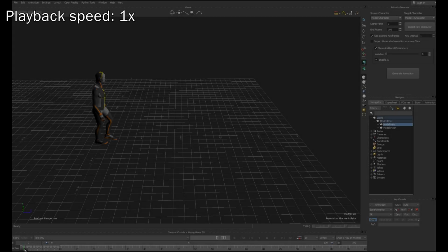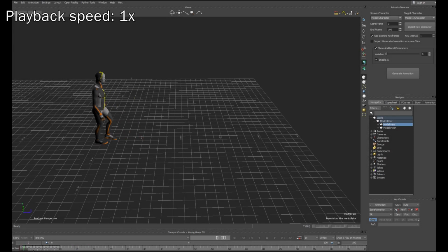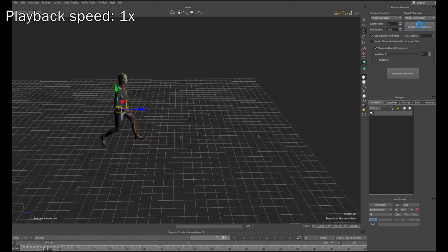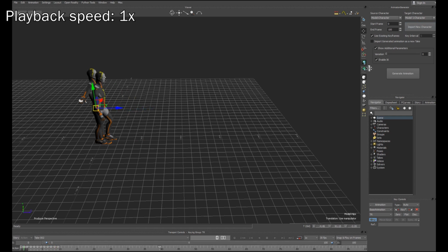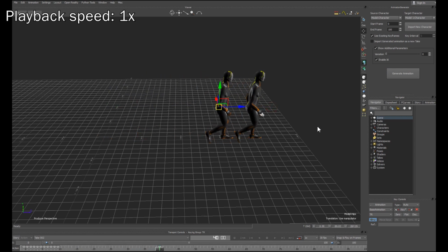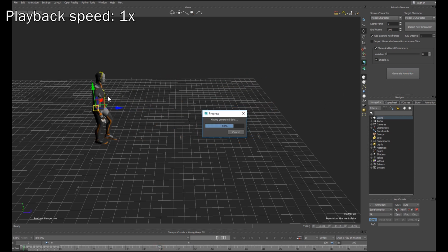To qualitatively assess the performance of this model, we embed it in a custom motion builder plugin so it is easy to use in a production scenario. Here is a simple workflow example where walking motion is extended and modified by simply copying and dragging its last keyframe in time and space. The generation of the in-betweening takes less than 2 seconds. The gait can be adjusted by simply moving the target frame and clicking the Generate button again.